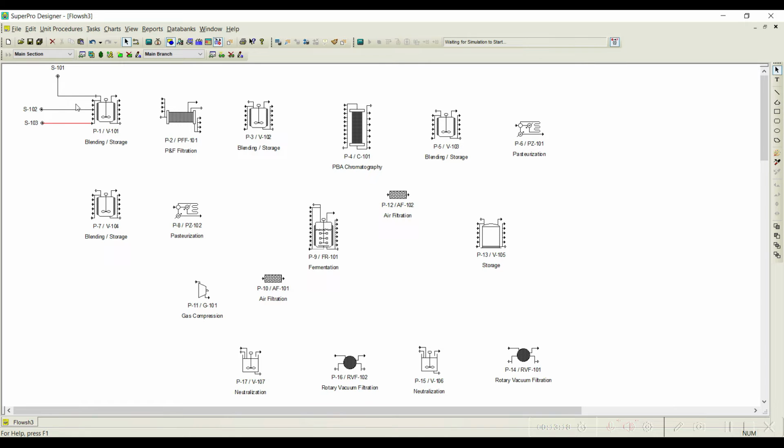So now three input streams are connected, that is, for carbon source, two water streams, and I need to connect whatever is coming out of the mixing tank, from the mixing tank, to the filter. So here you can see the output is connected to input, output is connected to input. White ones are default ports, you can select them, and these are additional ports. You can notice each equipment comes with one default input and output. It is mandatory that we connect them, and additional input and output streams are also available in case you require.